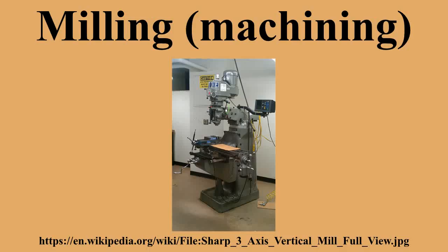In the bed mill, however, the table moves only perpendicular to the spindle's axis, while the spindle itself moves parallel to its own axis. Turret mills are generally considered by some to be more versatile of the two designs. However, turret mills are only practical as long as the machine remains relatively small. As machine size increases, moving the knee up and down requires considerable effort and it also becomes difficult to reach the quill feed handle. Therefore, larger milling machines are usually of the bed type.